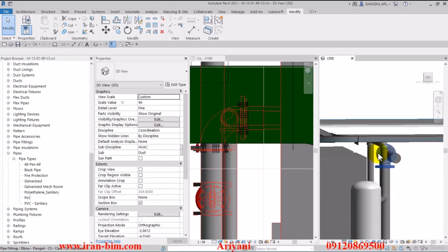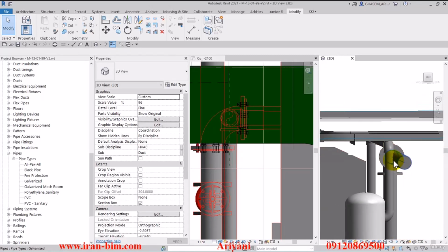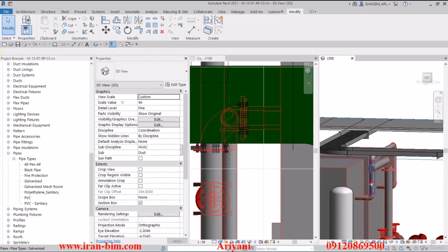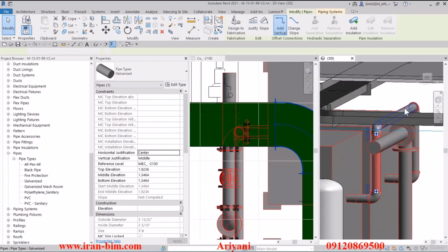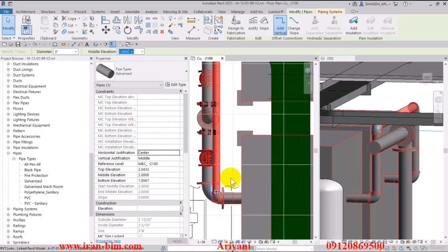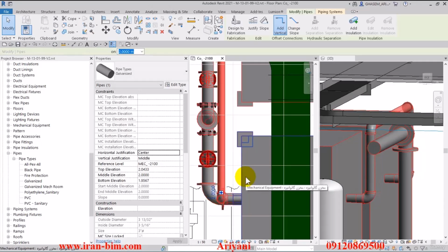And right now we can spot a small clash occurring with the pipe right here. So we've reserved too much space and depth for this, and we'll have to decrease it. I'll select the pipe up top, which we can see in the 2D plan right here, and I'll move this inside using the arrows on the keyboard.